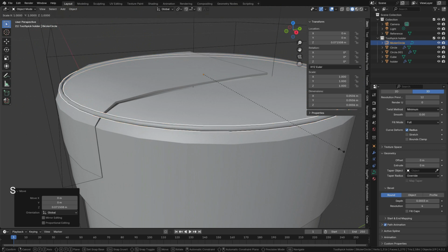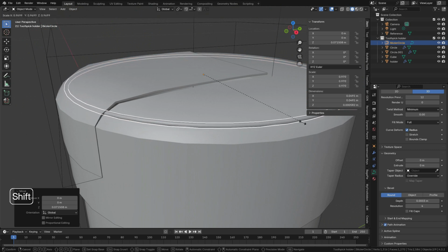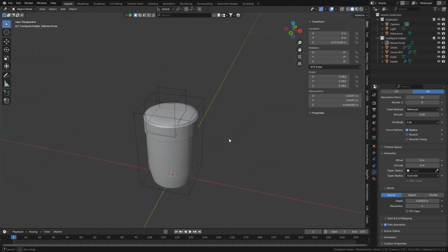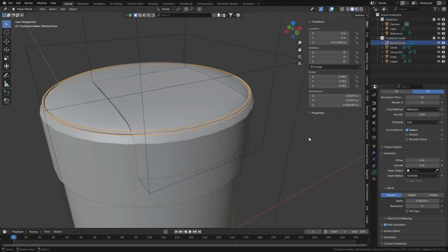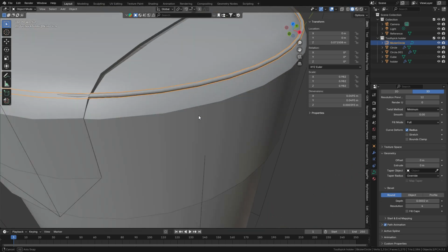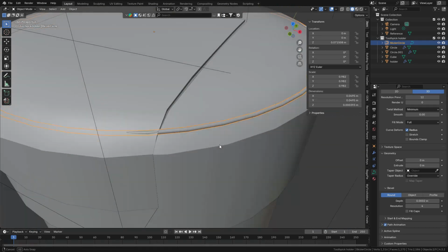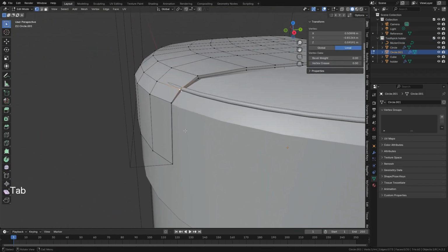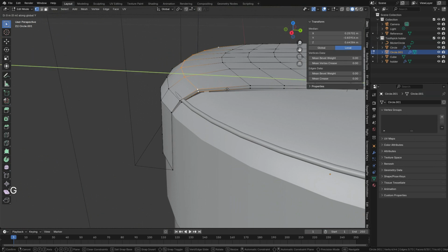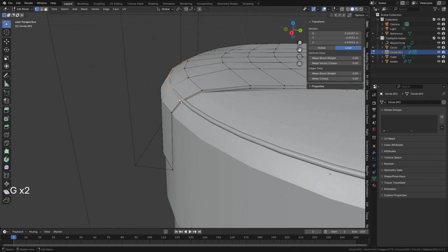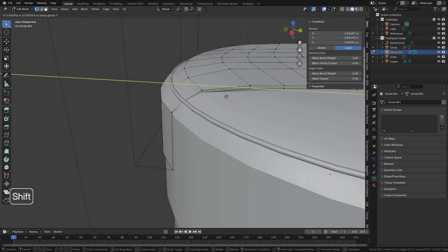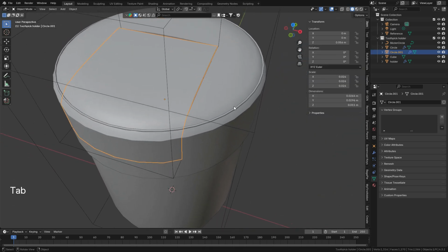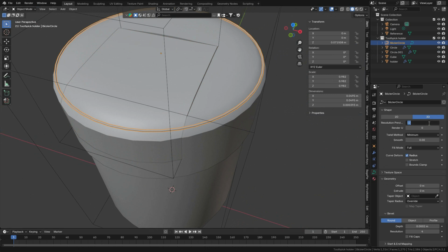Alright, so then we scale it. Scale it, it just touches the cap right about here. Maybe we'll make it even smaller. Make it 0.0002. Beautiful. So all we have to do is go to edit mode and then push these vertices so that you can see it. Nice. Okay. We want to increase our resolution to about 32.